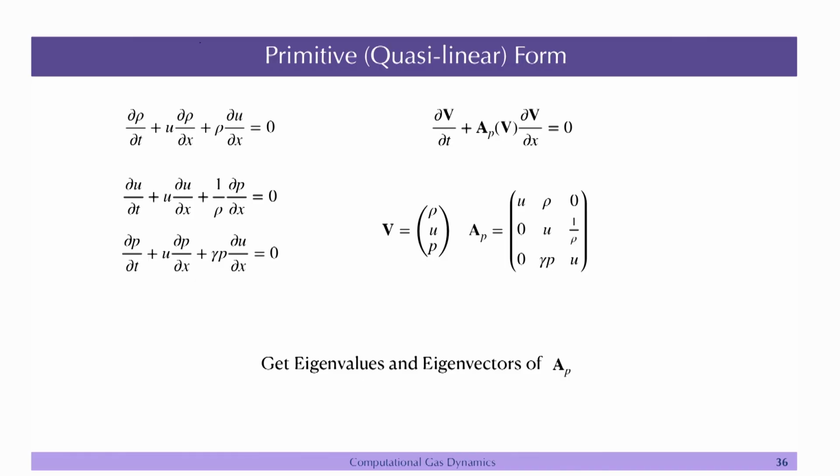What we did is basically we will do it for 1D. Now, you may ask the question that most of the flows are 2D or 3D, so why are you doing it in 1D? Even if the flow is 2D or 3D, what we are interested in is the flow which is coming normal. Let us say it is a 2D case. You have this normal direction, and there may be a flow happening here or here, whatever direction you have. So, what you have to do is take u dot n, which you call u normal or u perpendicular.